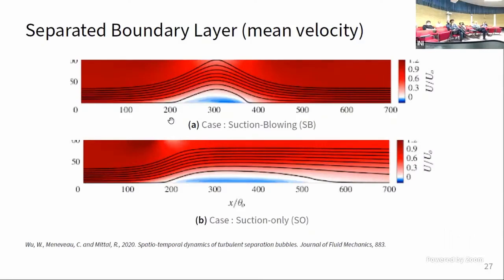At the top boundary, you can take that pressure gradient or that velocity profile and apply it to the top of your computational domain, and that will induce a similar separation to the case of an airfoil. These notations I'm just using the same as the quoted paper. What the suction and blowing implies is that there is some suction that introduces an adverse pressure gradient. As a result of suction, you have an adverse pressure gradient and your flow separates.